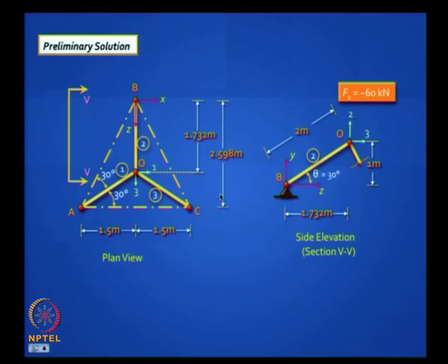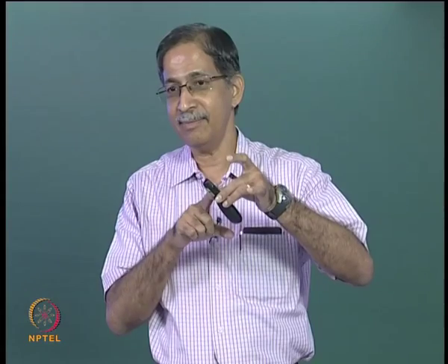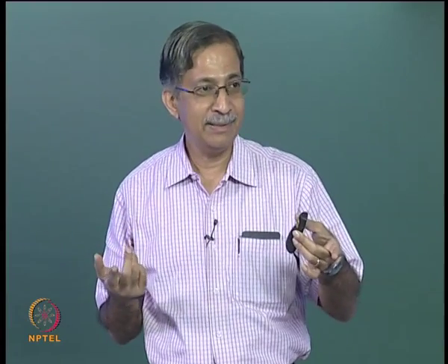Now without doing any calculations except extremely simple ones, can you tell me what is the force in each of these legs? Will the forces be equal? Yes, tell me the value. The total weight is 60, so 60 divided by 3 is 20? No sir, come on. How do you get it? Common sense, how do you get it? The vertical component is 30. Of the axial force in the bar, each bar must be 40 in each. Is it clear? Yes sir. Okay, let us see.